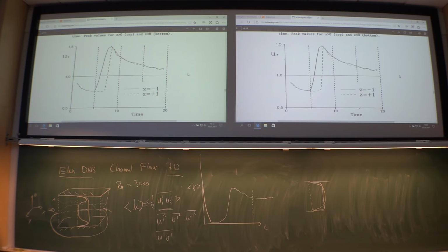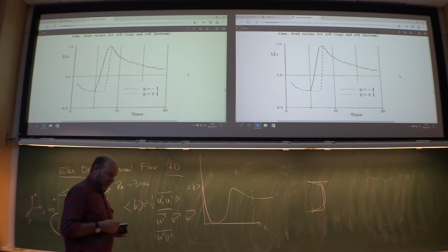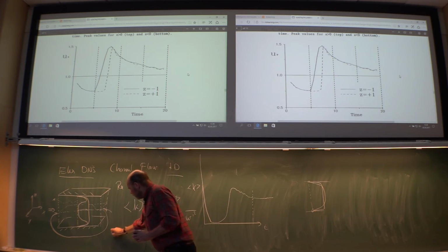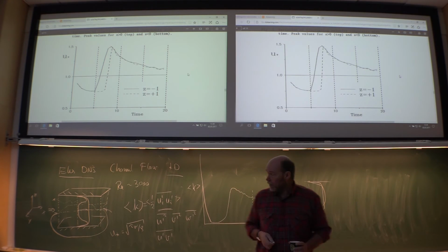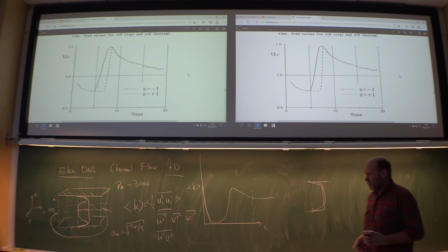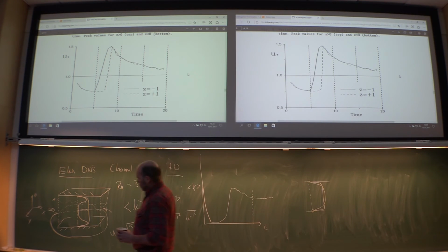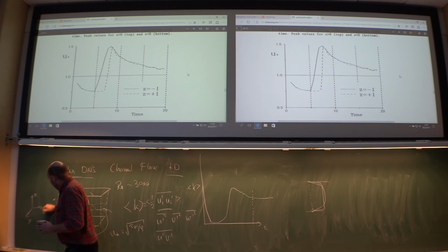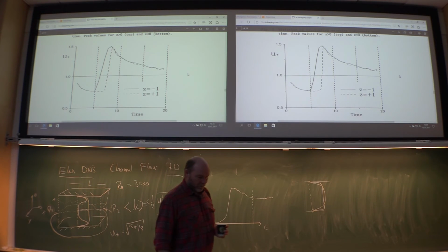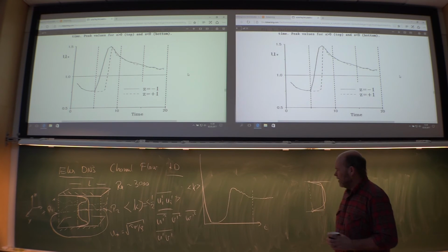The wall shear stress, or here the skin friction velocity, had something to do with the wall shear stress. And now remember this problem here. You have been given the driving force in the problem, say the pressure difference. You have a pressure 1 here, pressure 2 on the other side, over a length L. Then you know the pressure gradient. That's given externally.